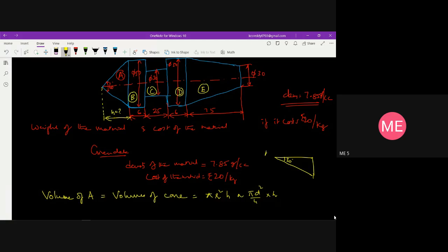So I have A and then B and C. So the BC length is also known. From here to here, the total length is 50, so it is equal to the radius, that is 25. Because I need to find out the AB length. So if I want to find out the AB length, what angle can be used here? So if I use tan 30, tan 30 is equal to BC by AB, opposite side by adjacent side, that is BC by AB.